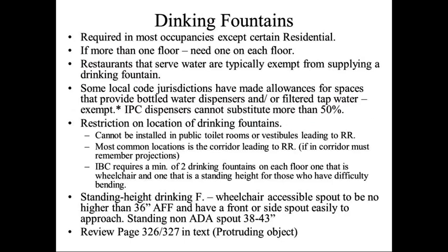Drinking fountains are required in most occupancies except certain residential. If you have more than one floor, you need one on each floor. Restaurants that serve water are typically exempt from supplying a drinking fountain, but some local jurisdictions have made allowances for spaces that provide bottled water dispensers or filtered tap water exemptions. Under the IBC, dispensers cannot substitute for more than 50%.